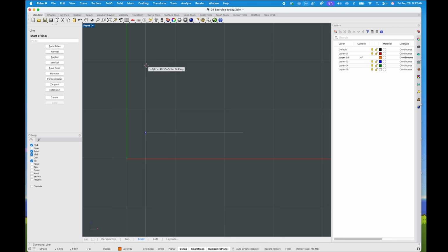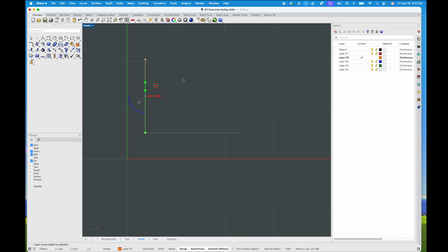However, let's continue and draw that line from one spot to another. In our case, I want to draw the line 1.5 inches. Enter. Voila, right? One thing that we can do, especially if I know I need one on the other side, is, you'll see that when you have O-snap, you can actually select a number of points, right? Maybe I want to connect to an endpoint, or a point, or a midpoint, or a center point, or an intersection.